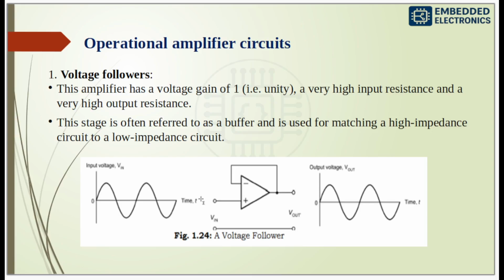The output is connected directly back to the inverting input. So this is minus, right? So that the feedback is 100% and V in is exactly equal to V out. This is the voltage follower.